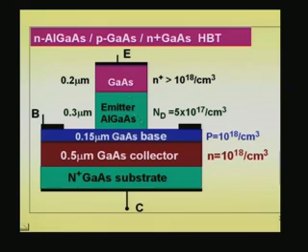So, this is just to show that you have got the gallium arsenide to make the good ohmic contact, lower band gap material. Emitter is AlGaAs, base is gallium arsenide, dimensions are all there, 0.2 micron, 0.3 micron, 0.15 micron. This is one of the typical structures that they made. People now talk of even smaller base widths like 0.1 micron to get to frequencies like 100 gigahertz. That is the frequency that people talk of, unloaded of course, just the individual capacity of the device. Collector gallium arsenide. So, you got AlGaAs, GaAs, GaAs structure.